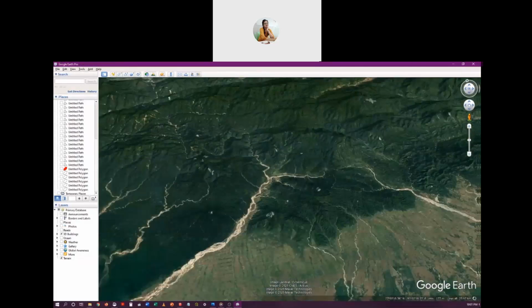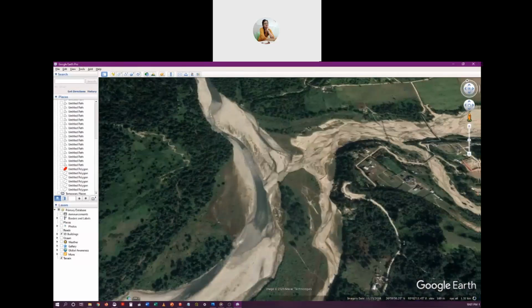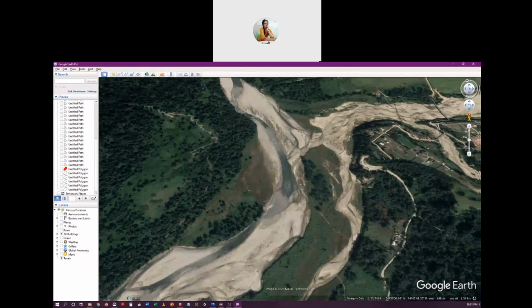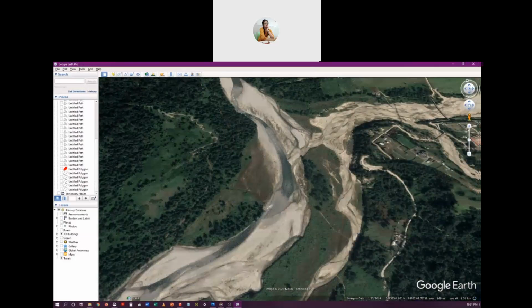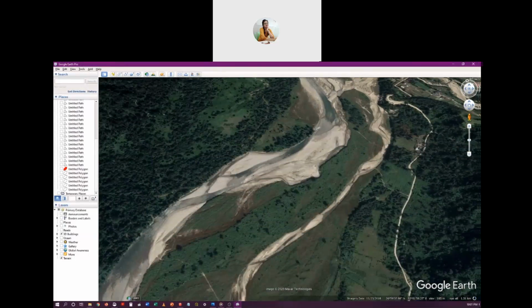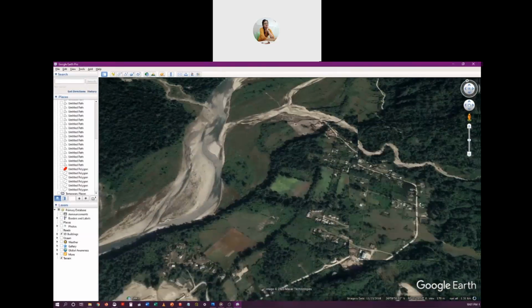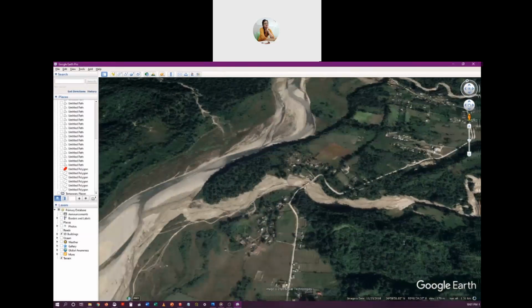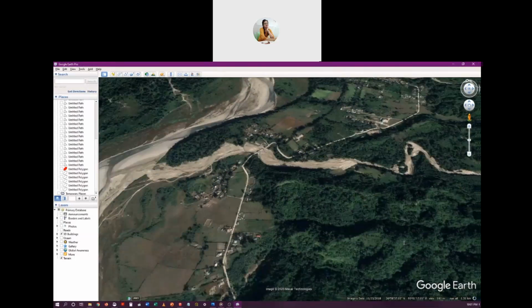That's why if we construct a project in the upstream regions, then although we have a greater command area, we will not be able to carry the water economically through a canal, because it will have to cross lots of mountains and natural drains. That is not a trivial task, because either you'll have to dig tunnels through these mountains, or you'd have to make cross drainage works.